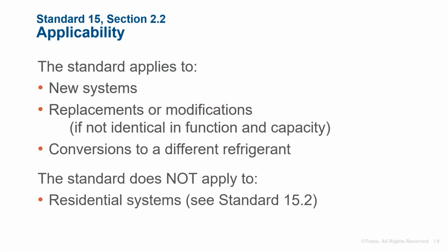Now, some of the requirements in the standard are general and apply to all system types. Others are specific to the type and use of the refrigeration system. The scope also clarifies that Standard 15 does not apply to residential systems that serve a single dwelling unit.